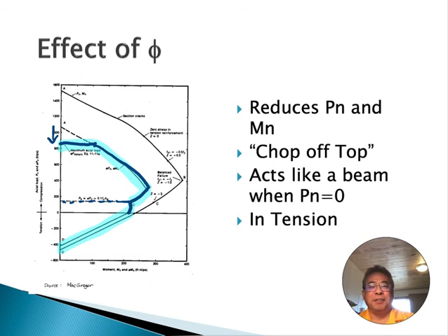So if you see that where it's squeezing in over there, you can know that diagram already has phi applied to it, so you don't have to take your values and multiply it by phi. Okay, so if you see something like this, the black one does not have the phi on it, the blue one has the phi on it.